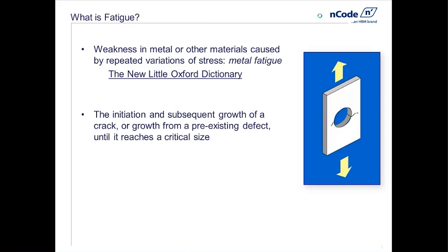And critical size can mean a lot of different things to different people. A crack in my sidewalk can be extremely long and not bother me. A crack in the crankshaft in my engine must be very short, otherwise we'll run into some serious warranty problems. So this idea of crack initiation and crack growth up until some phenomena that we consider to be failure is something we'll talk about a lot today.